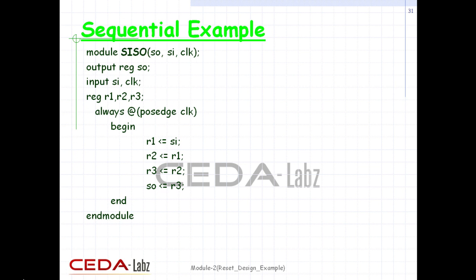Verilog description of serial in serial out register. In serial in serial out register, data will move in serially and result will be produced serially. That is why we define 3 registers for in-between shifting. Here in always block, sensitivity will have clock as event. As it is the sequential circuit, its triggering will depend on the clock pulse. Mostly, positive edge-triggered circuits are preferred.